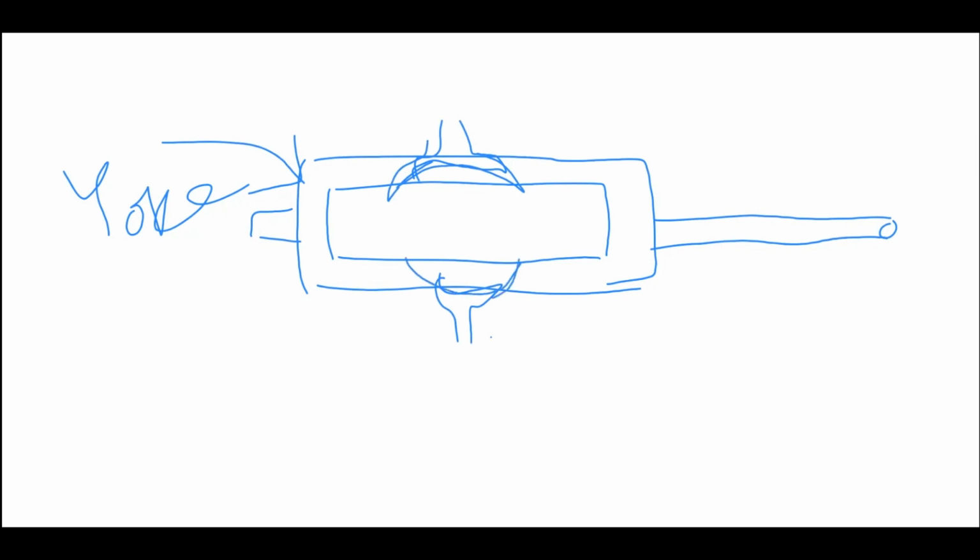Okay, so this is the pole arc. The flux lines are to be passed from north pole to south pole. Good enough. But since the pole arc is not covering the whole distance in a circular manner, some of the flux might leak from the desired path into the external circuit.